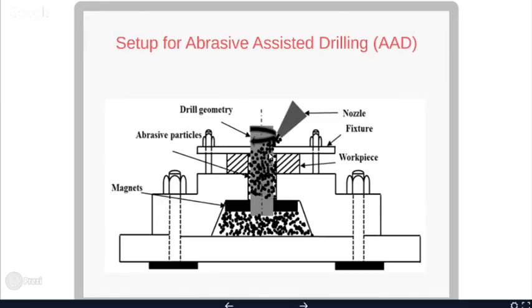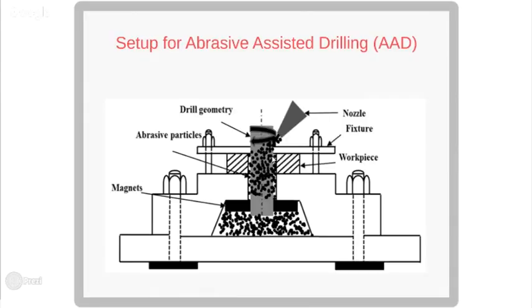Okay. During the rotation process, when the drill is rotating at a certain RPM, the drill carries the abrasive particles. Now here the cutting is because of the drilling action, the cutting action of the cutting edges, and these abrasive particles are entrapped in the fluid of the drill bit, and that fluid provides them a centrifugal force, and the free particles impinge on the surface of the hole wall.